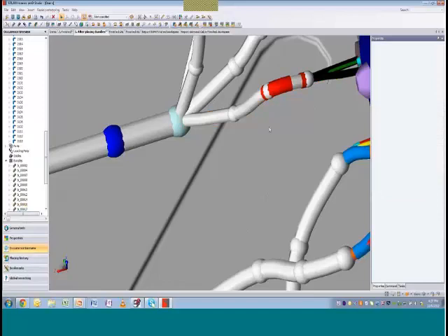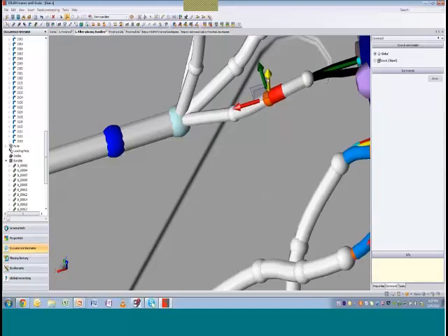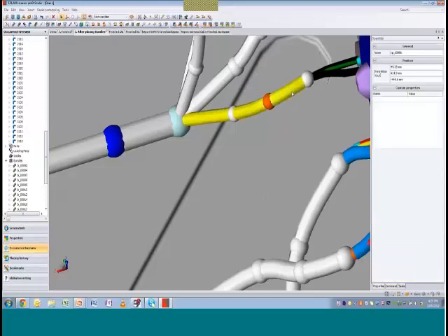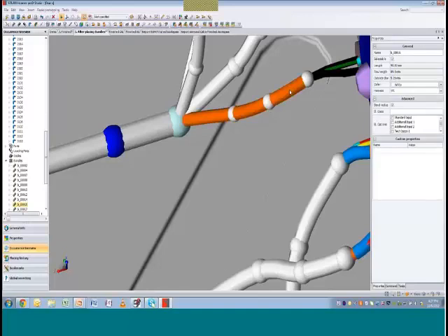And since the bend here is a little bit too much, we can easily adjust that so that later on we just alleviate the bend, and now we've taken care of the bend radius. So when we lay out our nail board, we will now have a true length. So our length is automatically updated, and we won't have to worry about having it too long, having that bend in there that could end up crimping a wire.